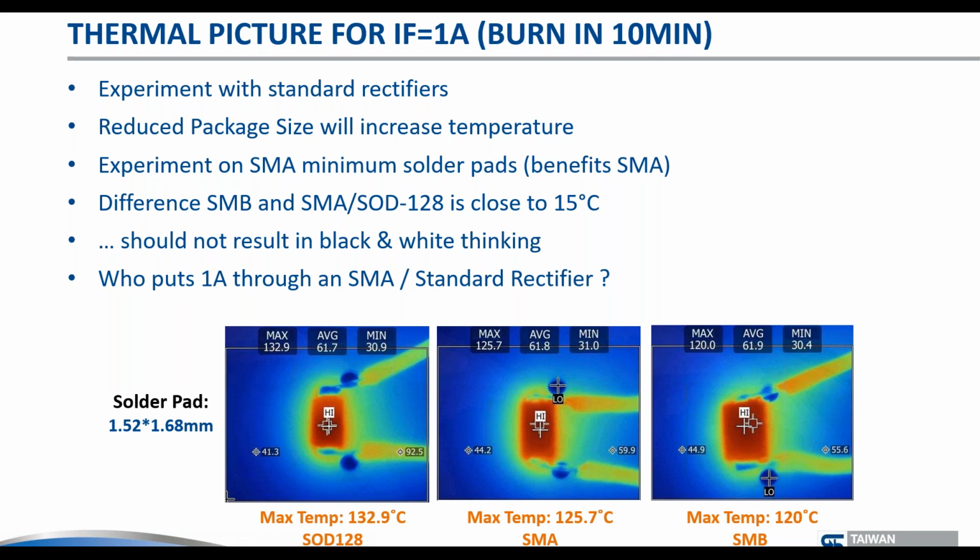I should mention here that this test was done at 1 amp on a standard rectifier. So you're talking about roughly 1 watt power dissipation, and thermal resistance in the area of 100 Kelvin per watt.